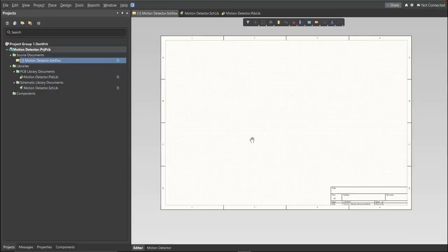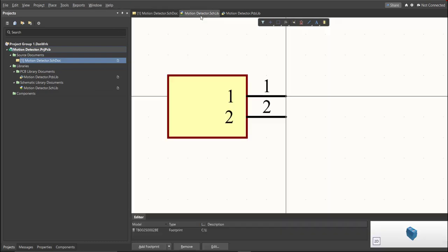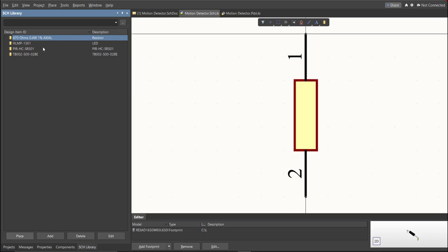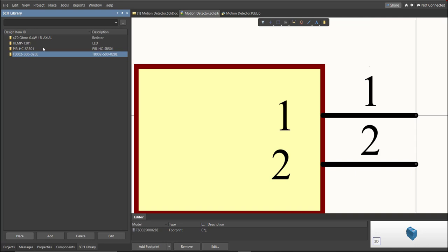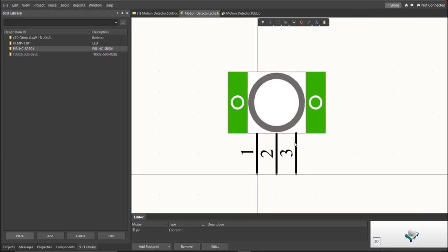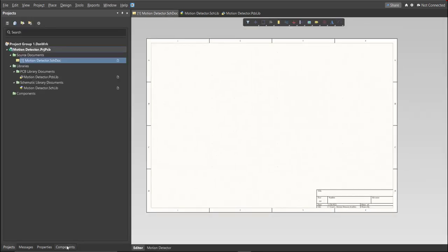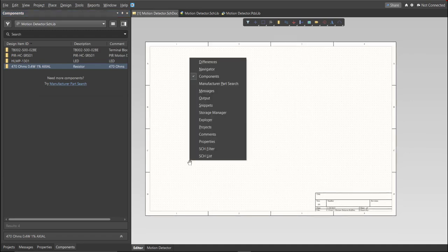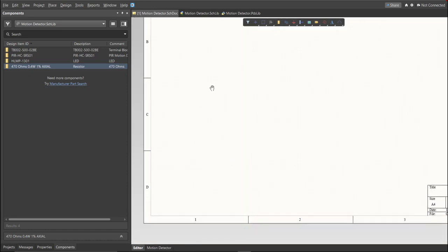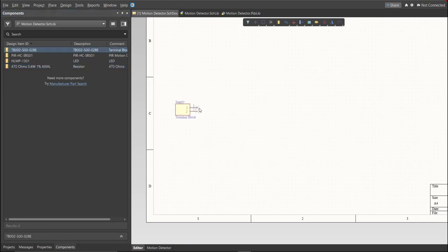After you finish all the components in the BOM list using a library loader, you can check here in schematic library panel all the added libraries. So these are the added libraries for this PCB. Next, we're going to put all of this in our schematic doc. So go back to the schematic doc and click on Components. If there is no component in your panel, just press K in your keyboard, then click on Components. Now you can see here the library for this project. So we're just gonna drag the library inside the schematic sheet.